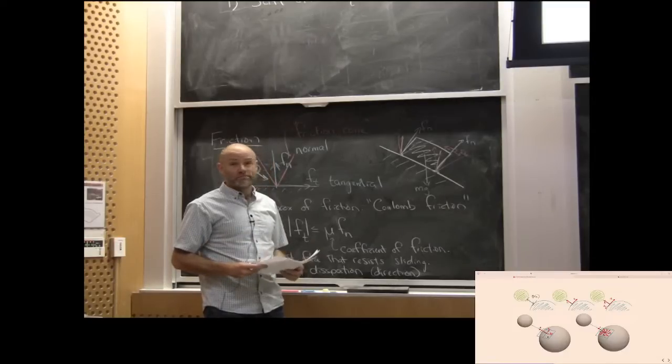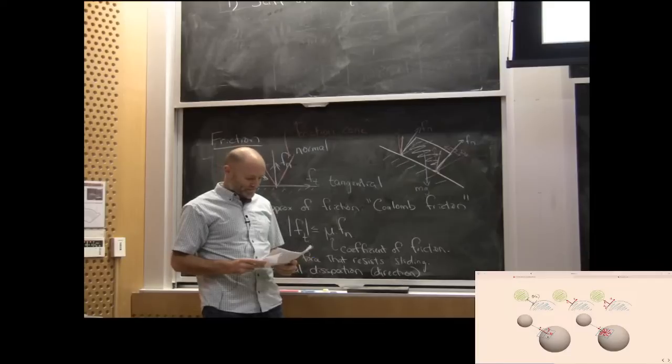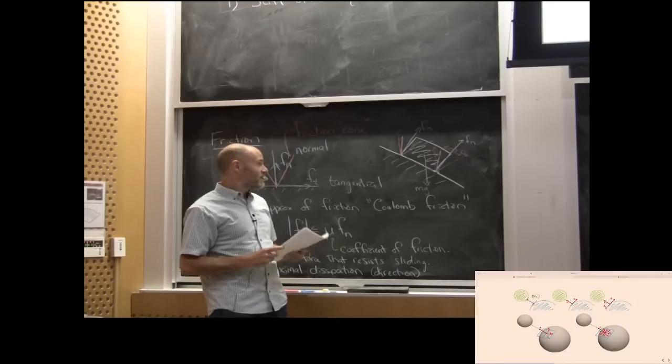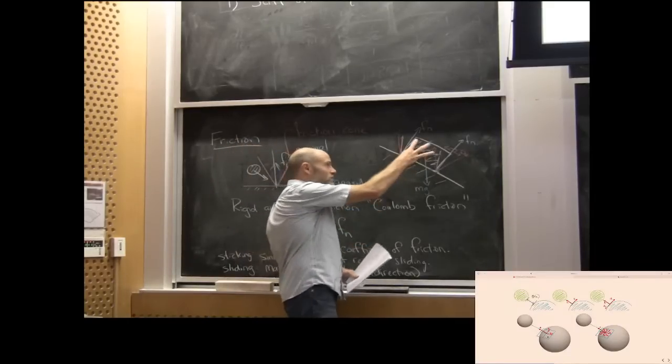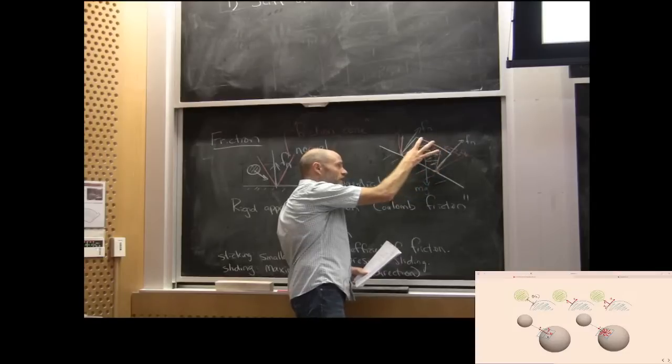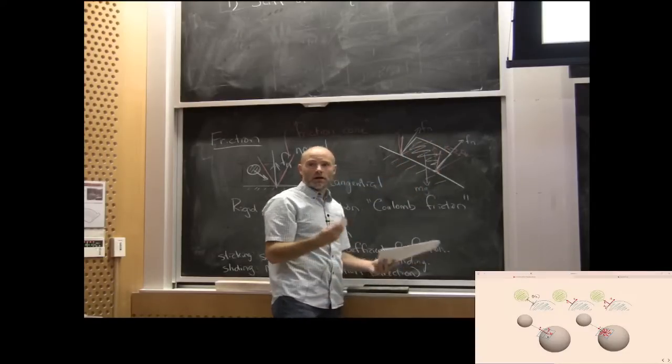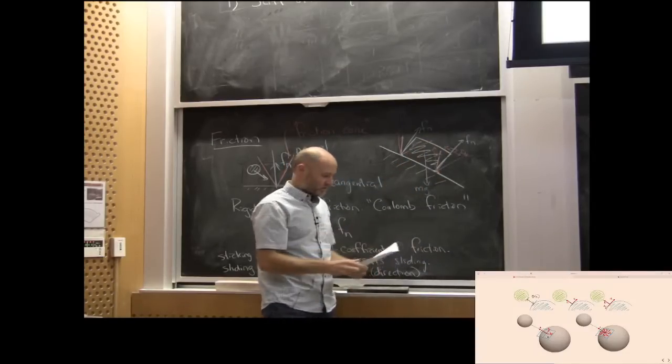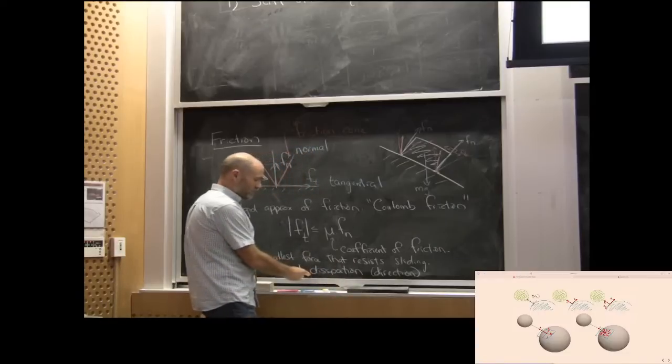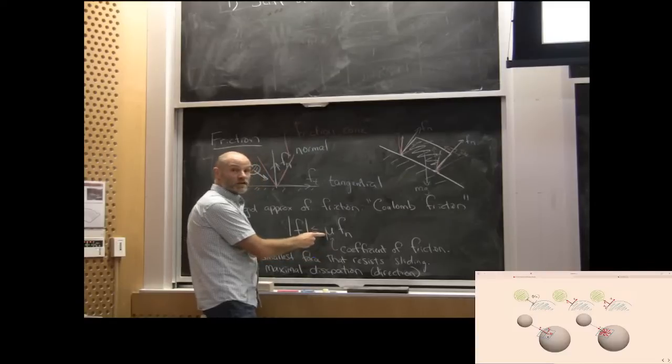Sliding friction is awesome, but I'm going to skip it. The rules governing what force you'll get when you do start sliding are similar. Typically, it's almost exactly the same with maximal dissipation, but most of the time people will say that your mu decreases once you start sliding. You'll have a different coefficient of sliding friction than static friction.